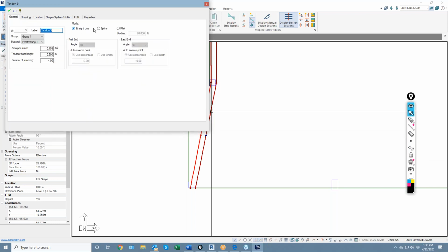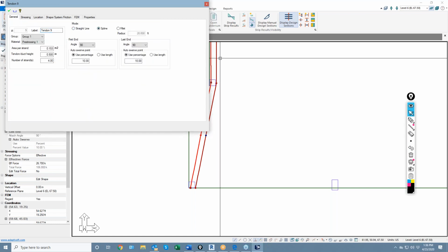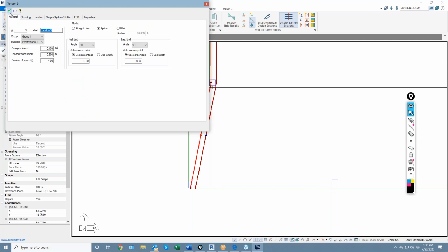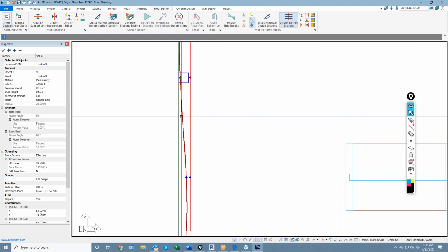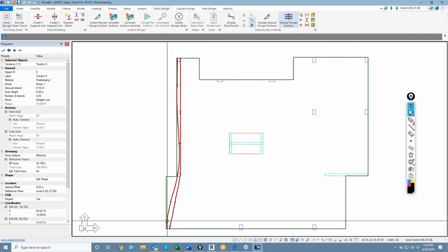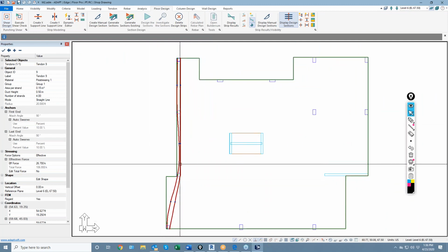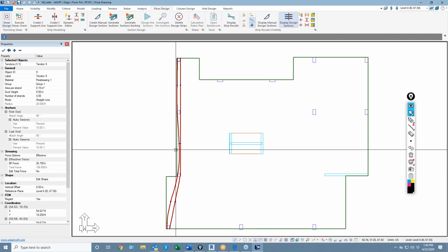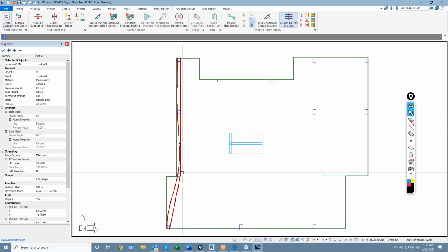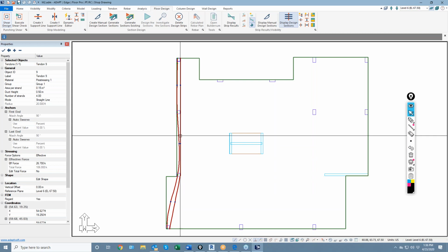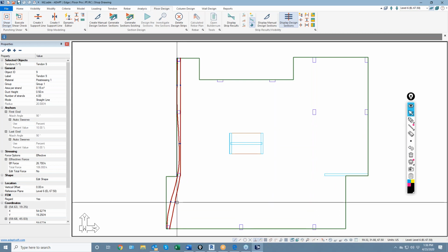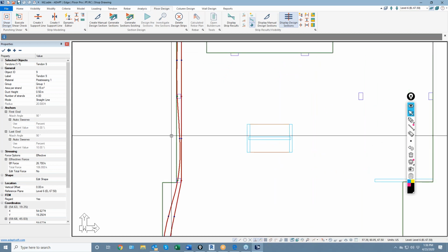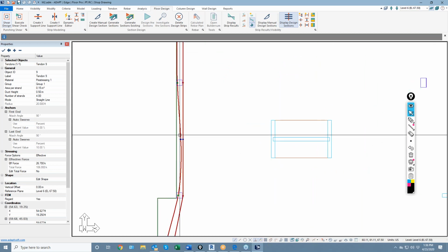But if we go to the general tab and change this to spline, we have a corner right there. I want to show the curvature of this cable around that corner. Using a spline, you can see that curves the cable, but you also have this back span that also has to maintain its shape relative to the shape function used for the spline. So sometimes that's not really realistic in terms of how the cable would be truly laid out in a shop when we're producing shop drawings.